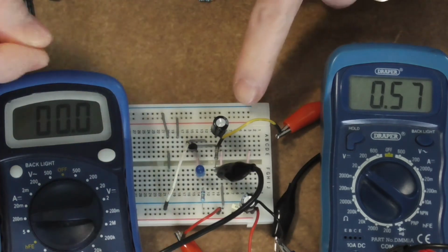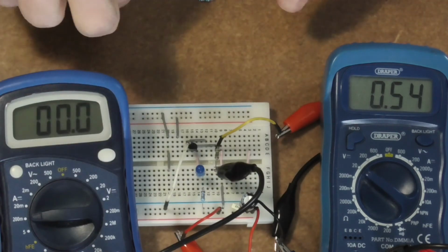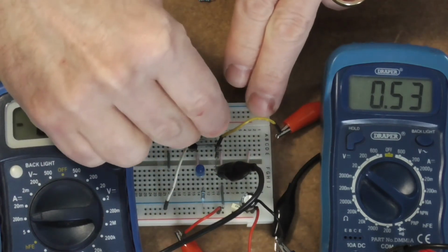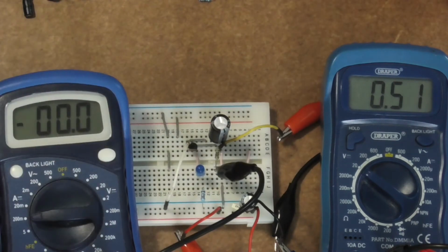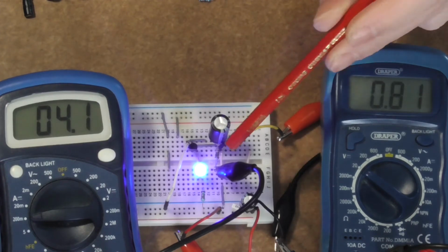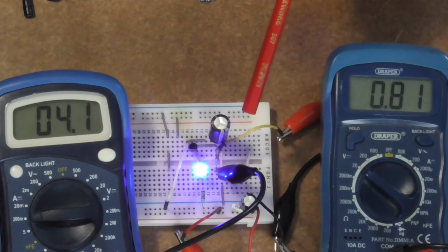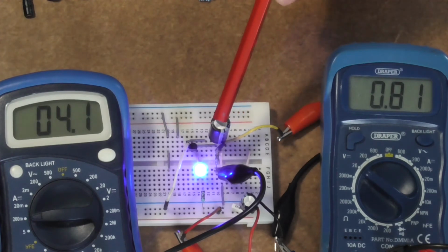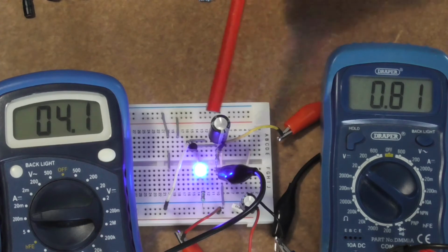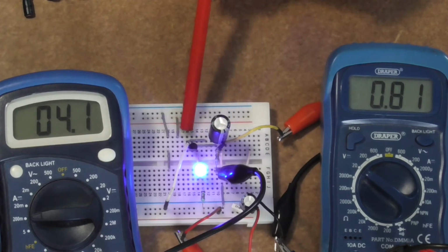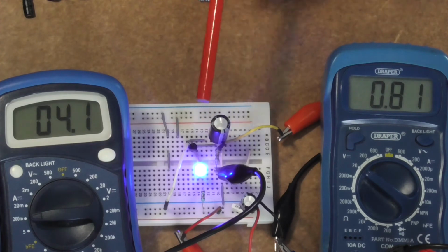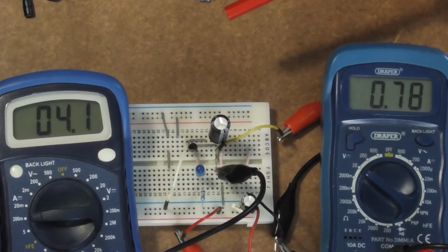So let's just jump on quickly to the next one. I've put in this 1000 microfarad and turn that on, and again it's basically almost instantly. This resistor is not doing much resistance, it's only a 1k, so it allows this capacitor to rise up very quickly to the 0.81 volts that it requires for this transistor junction to turn on, with 4 milliamps flowing onto the base, which is great, that all works fine.